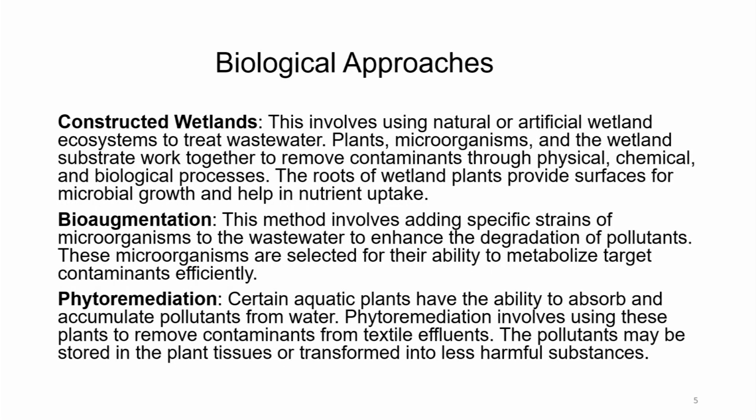Constructed wetlands. This involves using natural or artificial wetland ecosystems to treat wastewater. Plants, microorganisms and the wetland substrate work together to remove contaminants through all three processes: physical, chemical, and biological.